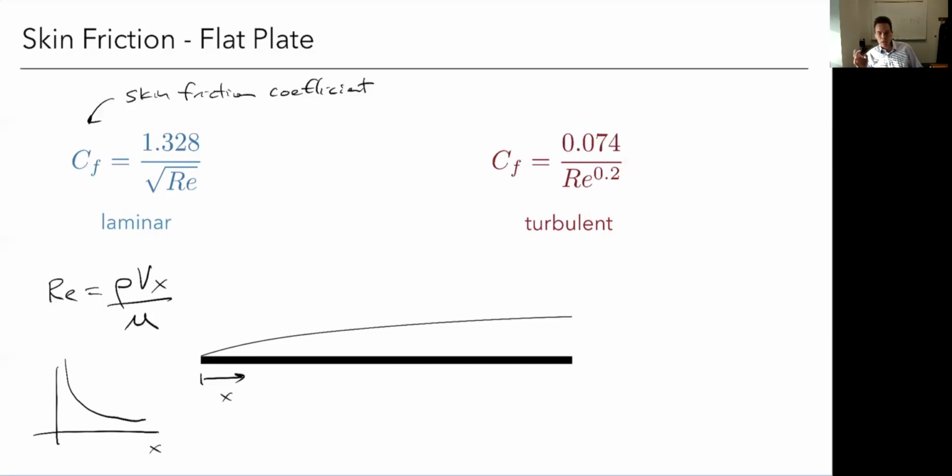That'll be actually pretty close because, for one, your model aircraft are not going to be as super smooth as, say, aerospace grade materials. You're going to have some rough edges. You're going to have propellers and you'll have some control surfaces, various things on your airfoil that are going to make it rough. So it's actually not a bad approximation to assume it's fully turbulent, especially because we're flying close to the ground in the planetary boundary layer where there's a lot of mixing. So I would do that, one, because it's pretty reasonable, but also because it'll be a bit conservative, which is probably best, right? To overestimate the drag a little bit.